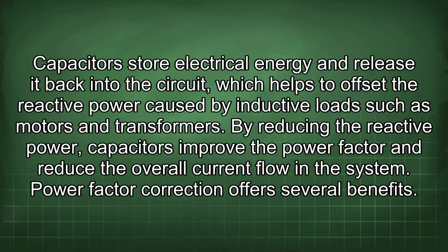Capacitors store electrical energy and release it back into the circuit, which helps to offset the reactive power caused by inductive loads such as motors and transformers. By reducing the reactive power, capacitors improve the power factor and reduce the overall current flow in the system.